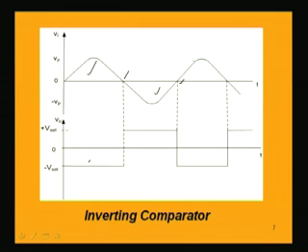Here it is crossing 0, again it is changing from positive to negative, and the direction of the crossing, either from positive to negative or from negative to positive, can also be detected from the output voltage, because at this point when the V saturation is jumping from negative to positive, correspondingly Vi is changing from positive to negative, that means it is crossing 0 from positive to negative direction.